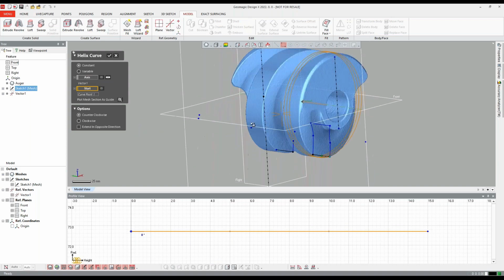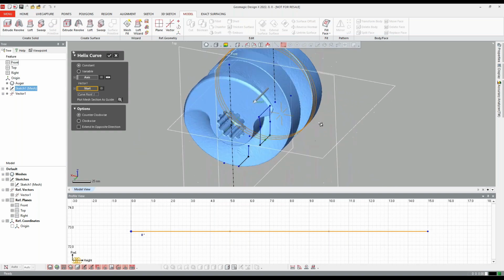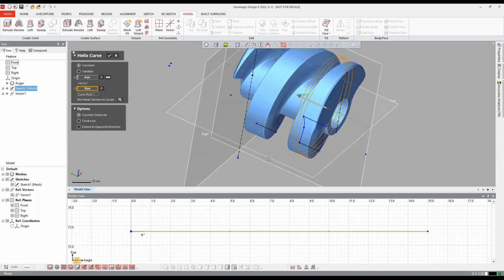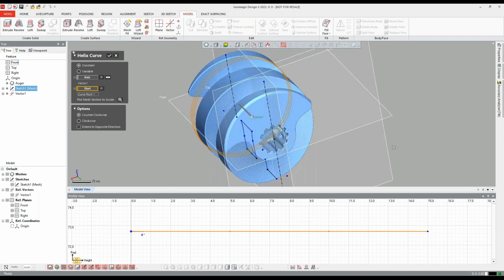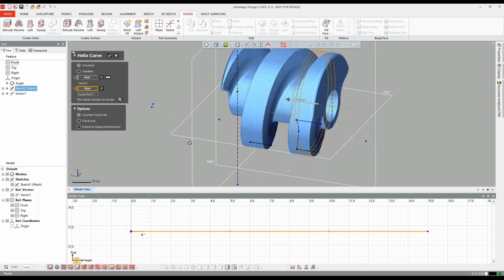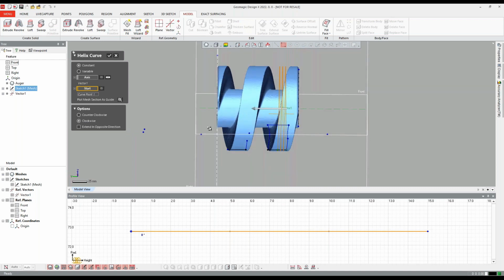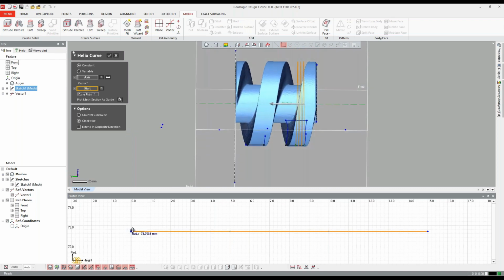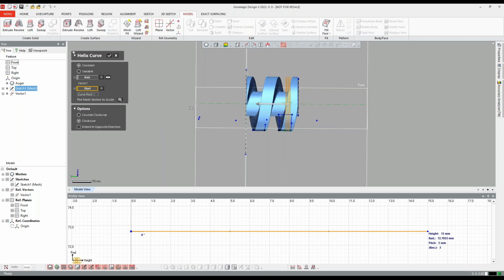We're going that direction. We can see that we are going counterclockwise, which is always based on the point direction. But anyway, I could tell that this thing is going the opposite direction, so I'm going to flip that. Our radius is already set. And then our endpoint is just arbitrary, set at like 15 here. We need to come in at the end anyway, so it doesn't really matter. And then we just need to put our pitch in and our 2 revolutions and stuff like that.